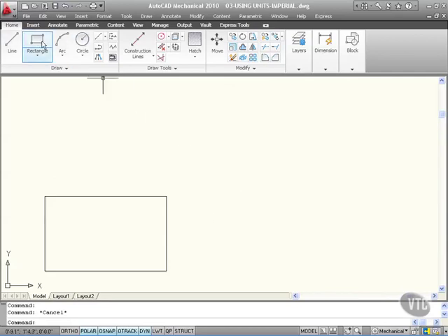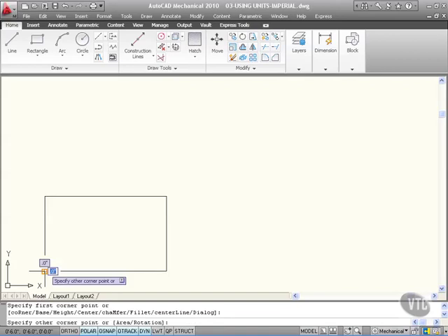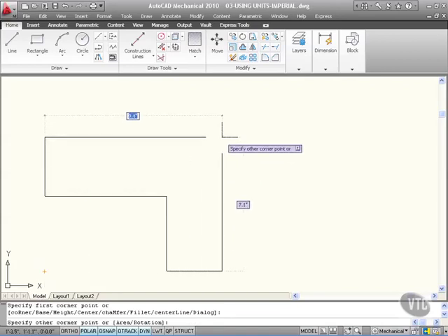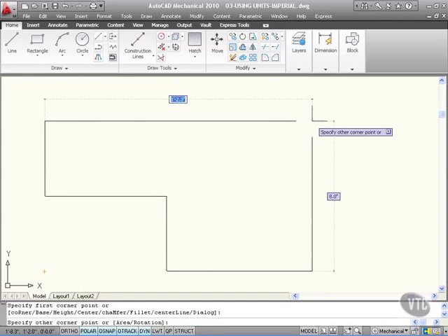So now I go to rectangle again, and I'm now going to click on this corner here. I'm going to use the object snap, the endpoint snap. So when I hover there and click, like so, and come out now, can you see, look, as I get bigger there, it automatically goes to that 1 foot, 2.3 inches in the X direction. Now to type that in, I'd put 1, and then I'd put that symbol there like that, then a dash, and then 3 inches, like so.